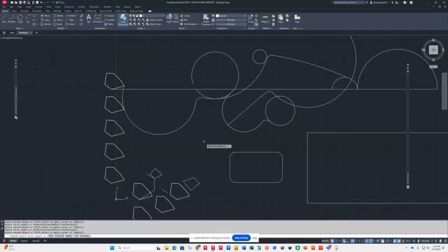And that's okay. When you do the frog one, which is the next to last, or is it the last? It's the last one, 212. When you do that one, there's one of them where you can put a fillet in, and it leaves your circle like it's supposed to, and it's fine. Okay, so that's the fillet command, and if you don't want it to trim, you can tell it not to trim. Like there's times where we do a thing called a run out. That's where you would tell it not to trim. But most of the time you want it to trim.